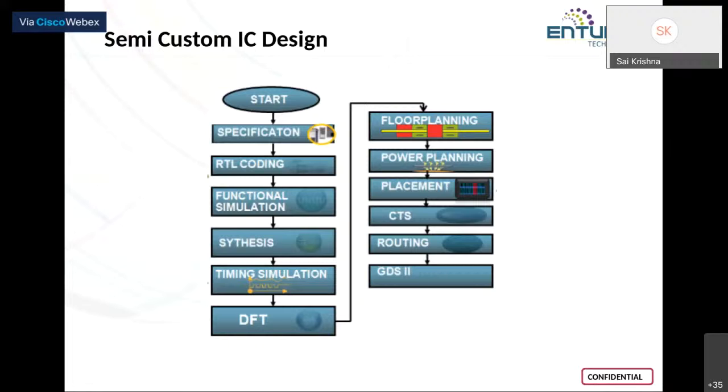So whatever functionality you have built, you will have to first verify that also. For that, you force certain input signals onto your design and check its corresponding outputs with respect to time. That is nothing but your transient analysis or your functional simulation. So be it full custom or semi-custom, once you have built your functionality, you are going to simulate it with a stream of input signals. And then once your functionality is verified, we move on to your physical aspects.